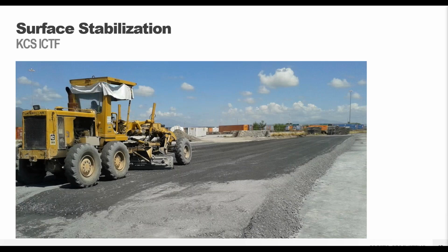So you can see the final wearing surface here. And so this is going to provide a nice solid surface to support the load, minimal maintenance required. In this case, they chose to include an asphalt tack coat as a surface stabilizer. So while the GeoWeb panels themselves do help prevent movement or shifting of the aggregate, if you do want that little extra peace of mind, adding a surface layer of asphalt tack coat or a low strength cement grout, something like that, can be used to ensure there's absolutely zero movement of the stone. Definitely still works with the GeoWeb system. It is a little bit extra on top for peace of mind. It is not required.